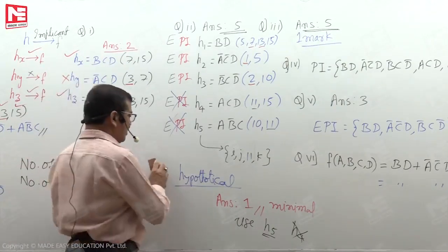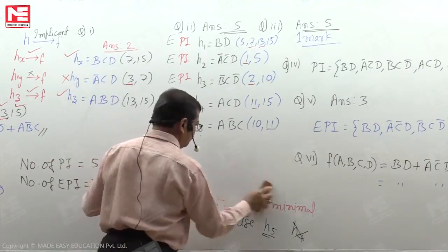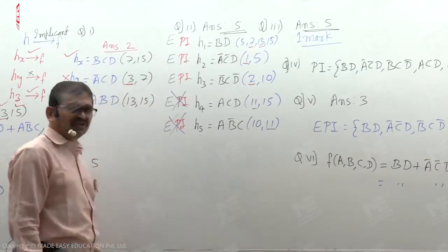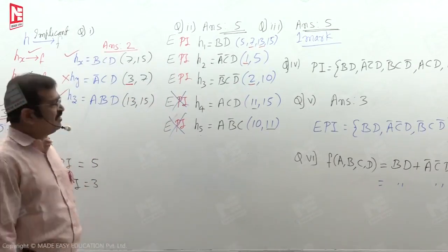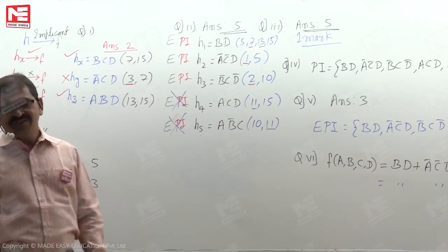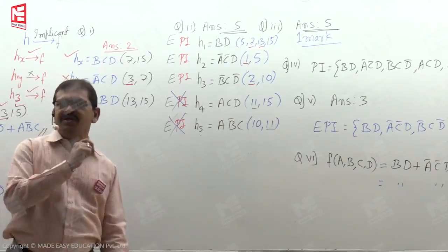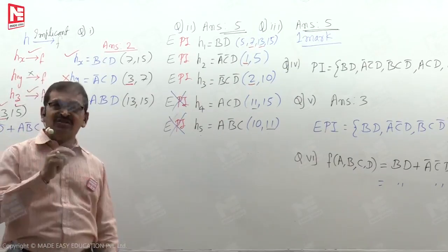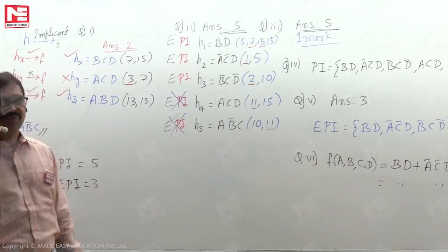But it is not the scenario in this example. In this example, both the subcubes are the same size. Hence, if we use any one of these, it is sufficient, along with the essential prime implicants. So the answer for the number of minimal expressions is 2.